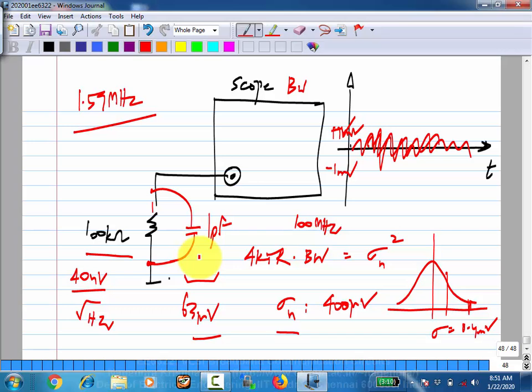Okay. So what I am trying to say is that sometimes we will calculate spectral densities, and in that circuit model the bandwidth limitation may not be obvious, like the common source amplifier I gave you, right? But in reality it will be limited either by its own output parasitic capacitance or the bandwidth limitation of whatever circuit is following it. Okay, it has to be.